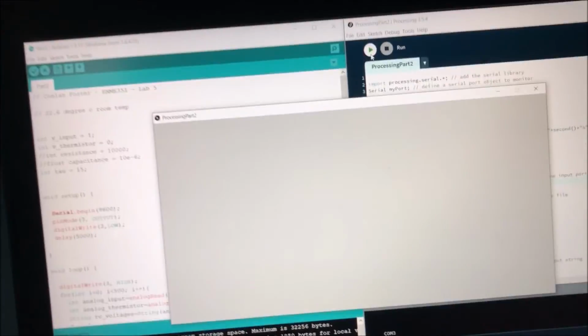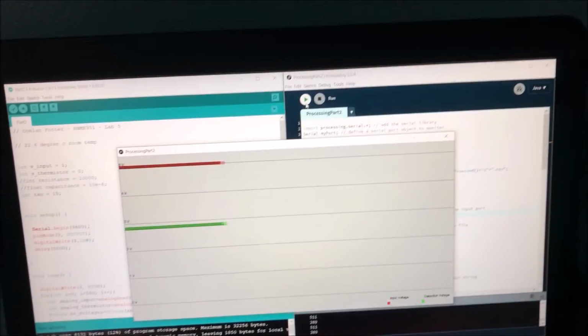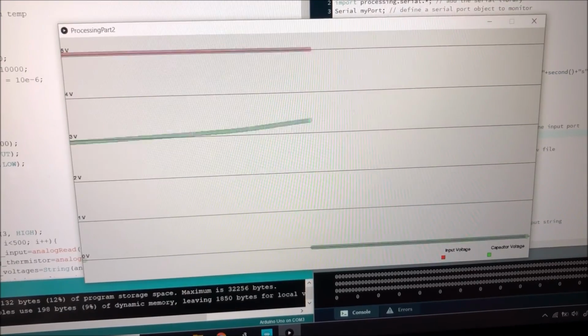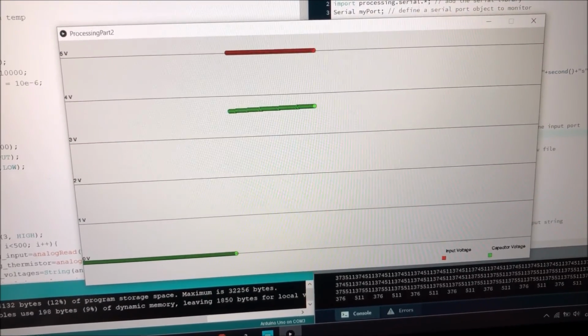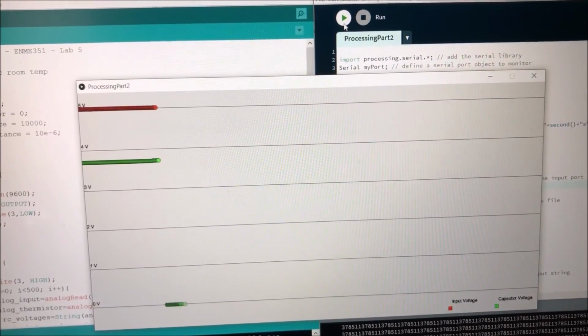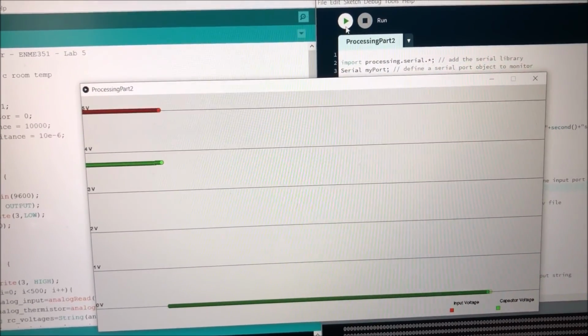In order to cool the thermistor, I bagged ice cubes, which have a temperature of around 0 degrees Celsius, and touched them to the thermistor. We can see the voltage rapidly rise when the thermistor is in contact with this much lower temperature. From my understanding, this change in temperature acts as a step in the voltage function equation, and as heat transfer is always a function of time, we can see that this is not instantaneous and it has to gradually change.